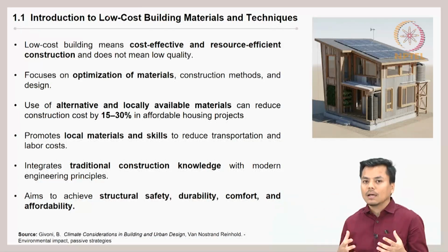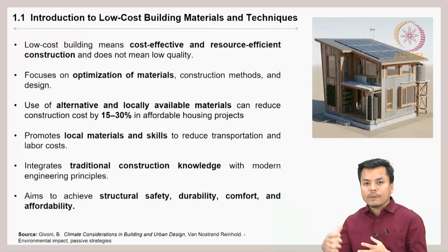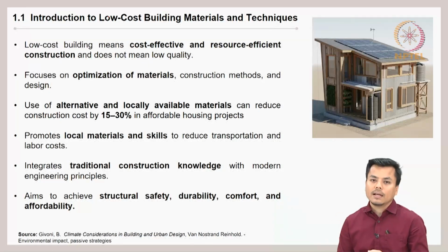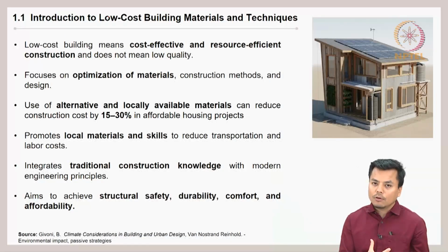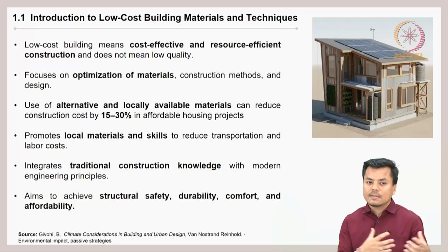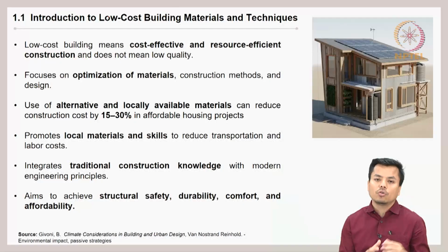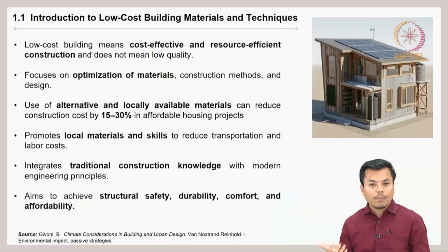So this type of construction method or planning is called modular planning, where a module is fixed. That means a unit is designed and there is a repetition of units in the construction. So that is called modular planning. If you go for that, then the formwork will be the same and will be repeated again and again, and also if there is any excess material available to you during the construction of the ground floor, the same can be reused in the construction of the upper floor. So this is the advantage of going for modular construction.